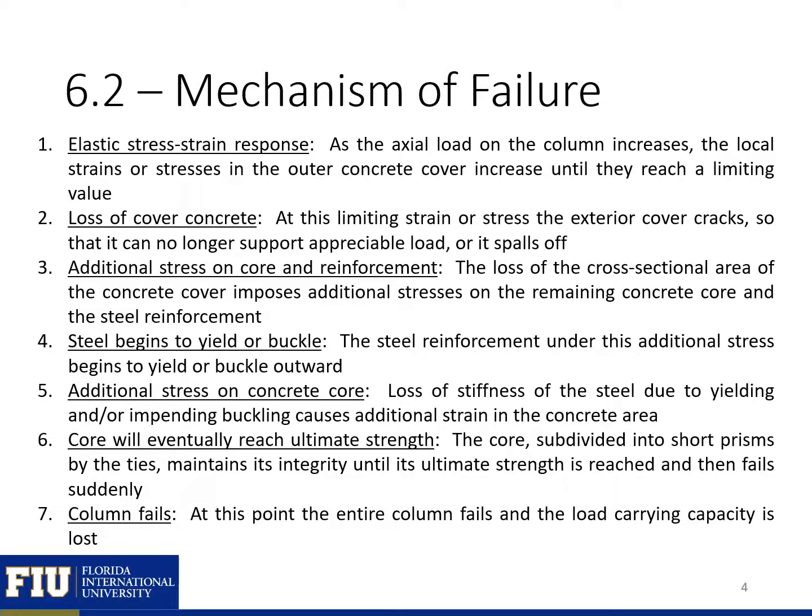We're next going to step through how these axial only members will progress to failure. They'll start with an elastic stress-strain response. So as the axial load on the column increases, the local strains or stresses in the outer concrete cover increase until they reach some limiting value. So we're going to be elastic until we lose the cover of our concrete.